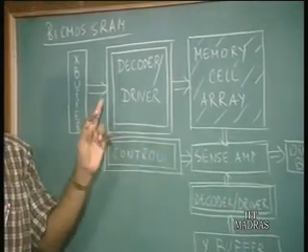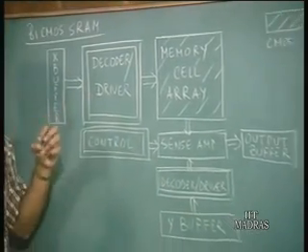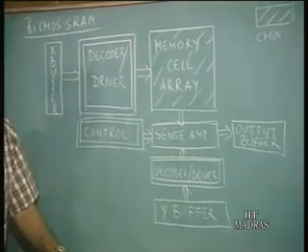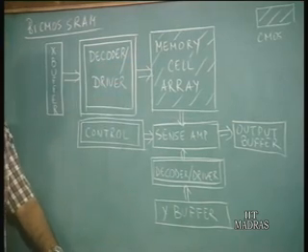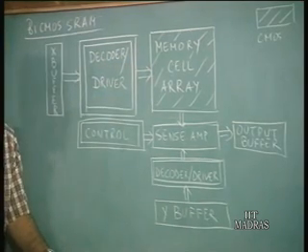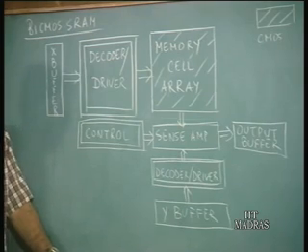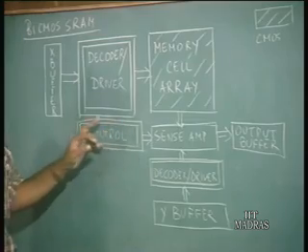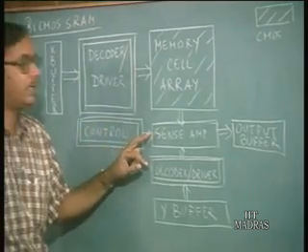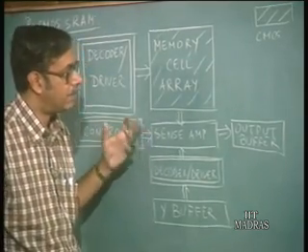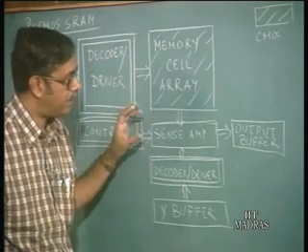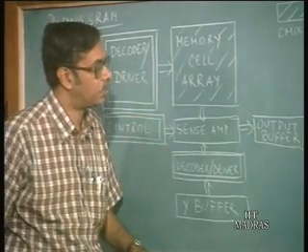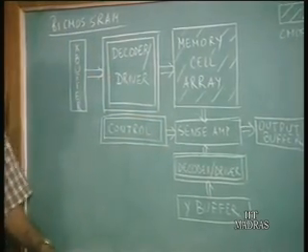The decoder drivers are BiCMOS because BiCMOS is capable of driving very large capacitive loads. The word lines and the data lines represent very large capacitive loads. Then the sense amplifier, on the other hand, is completely bipolar, because the bipolar transistor has a very large transconductance and is able to sense very small voltage differences between the data and data bar lines.